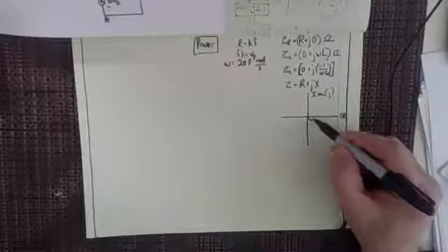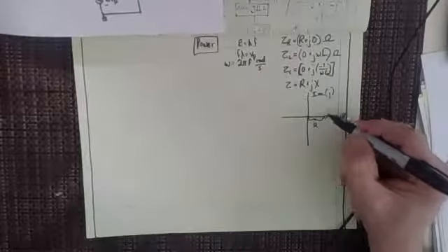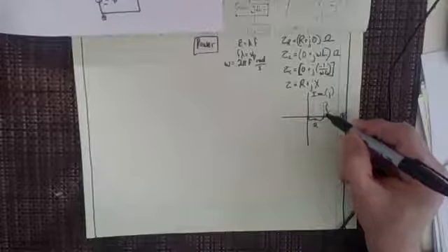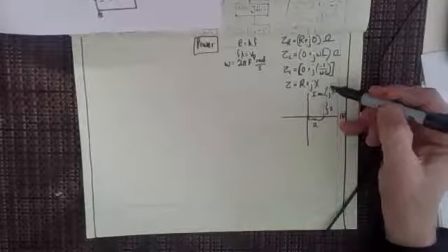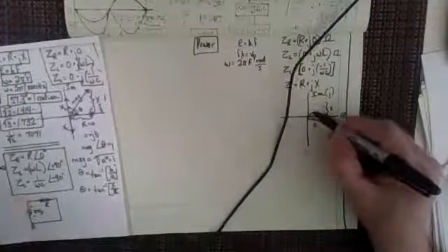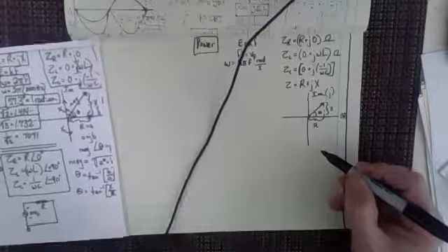But we've got the real, and so anyway, when we're looking at what the impedance of something is, if we know that this is R, our distance along the x-axis, and then we know that this distance here is X, we can describe this in a complex number notation like we have there, or we could describe this in a magnitude, like a vector representation, right? So we've got a magnitude and an angle of rotation off the real axis. So how would I really write that?